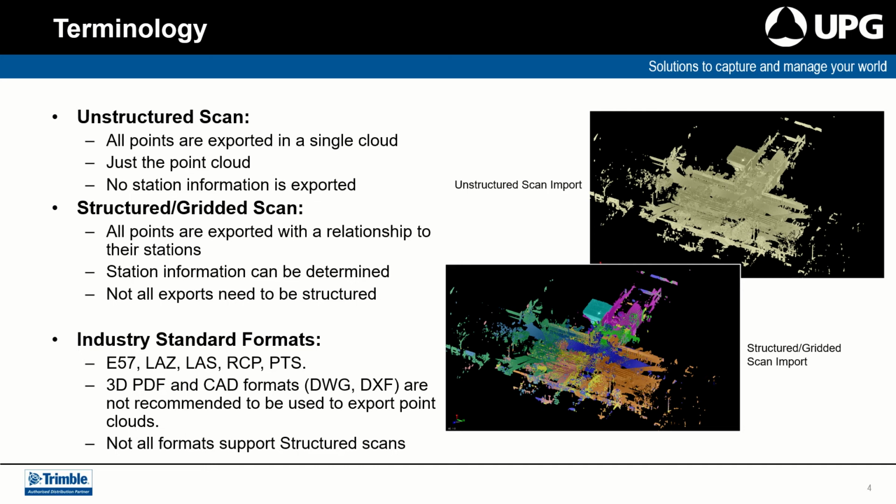3D PDF and CAD formats such as DWG and DXF are not recommended to be used to export point clouds or for handling point cloud data. They can be used for the CAD data that comes out of point clouds, however not for storing the point clouds themselves. They are not designed to handle the large number of points in a point cloud.